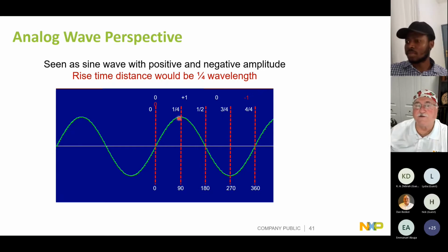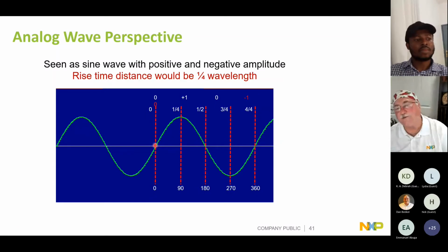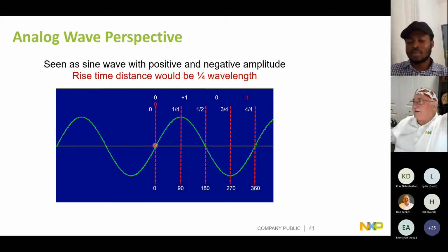And at that point, the voltage is at maximum and it's stopped changing. So it's not being converted into a changing H field at this point in time. So if you're looking at a structure that's a quarter wavelength long, and you take a signal from a 50 ohm cable, and you put it into a dipole antenna, which is a 90 degree.